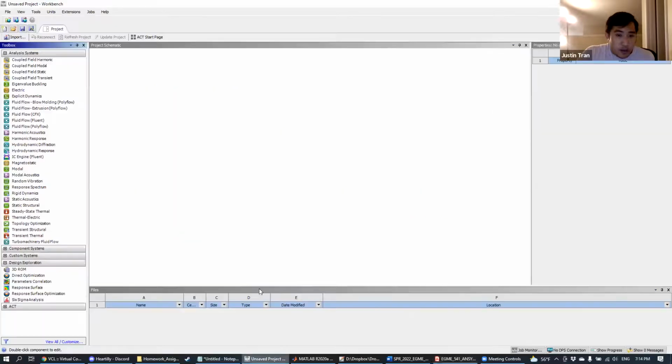If you open up Ansys Workbench, this is the first thing that you're going to be looking at. The first step is to select the type of analysis. You can use finite elements to solve for a lot of different types of physics and systems.